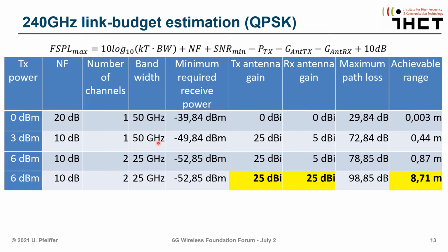When you really do the math here, you see that for anything that seems practical at the moment, you can only get to very short ranges. The only way really is to include high directivity transmit and receive antennas. It is not expected that the hardware will be making much improvement on transmit power or noise figure that is orders of magnitude better than what you can have today.